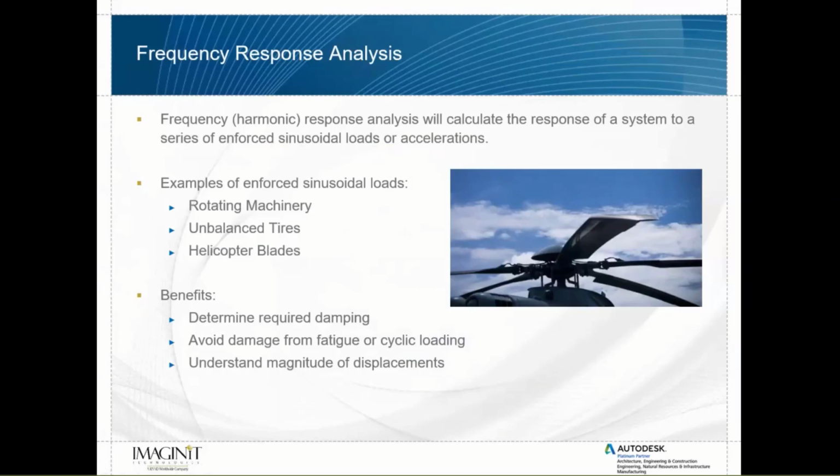So what we want to do is determine, based off of that sinusoidal input, what amount of displacement and stress will we see in our system? And will it be significant enough to cause damage? Will we be going beyond a specified displacement range? Maybe we have some tight clearances. So using frequency response, we can go ahead and determine what our required damping is going to be. So get an idea for what level of damping will reduce the displacement to an acceptable amount. So you can play around with the damping and try out different damping values to determine what's going to be best. You can avoid damage, which is a really key one here.